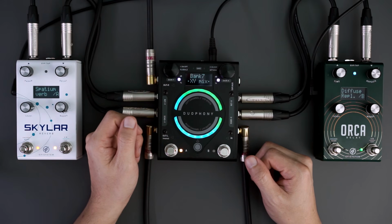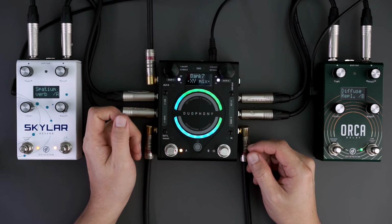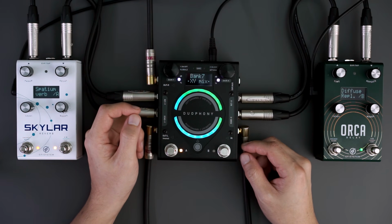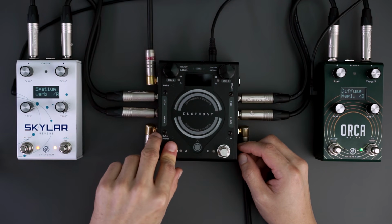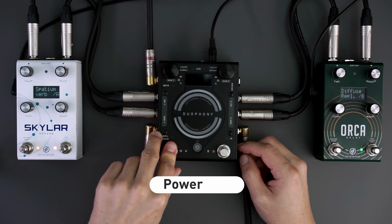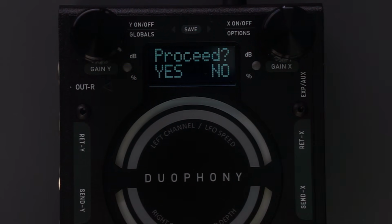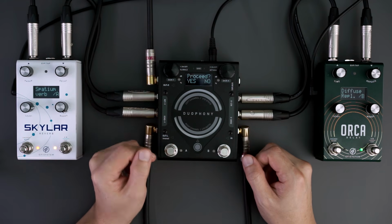There are two kinds of resets in Duophony. One is the factory reset, which will revert all the presets to factory settings, and the other is the global reset, which reverts the global configurations to factory settings. To perform the factory reset, begin with the pedal powered down. Press and hold foot switch A while applying power to the pedal. Press foot switch A to confirm the reset or foot switch B to cancel.